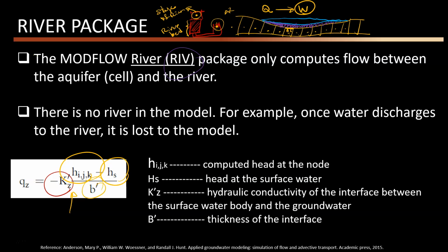Sometimes I see that some people get confused, but you need to pay attention to the fact that we are talking about groundwater models. Whatever you may see on the surface of your conceptual model, we actually don't have in our groundwater models. We don't have a stream or a lake. We just think about the cells buried under the ground. What we can do is consider how the river or the lake contributes to our system, and simulate the impacts of those surface water bodies on our groundwater. So be careful: we are not going to design or model the surface water bodies here.